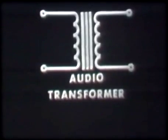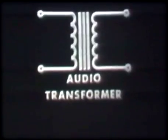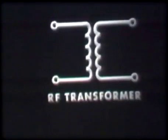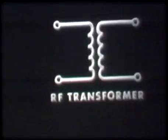Like the power transformer, the audio transformer, too, is usually constructed with an iron core. At frequencies above 20,000 cycles per second, the RF transformer comes into use. At these frequencies, hysteresis and eddy current losses in an iron core become so great they have to be prevented. Therefore, RF transformers generally have an air core. The schematic symbol for an RF transformer, then, is easily identified by there being no vertical lines between the primary and the secondary coil.